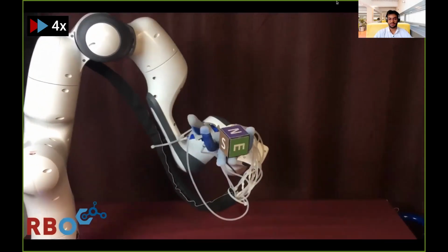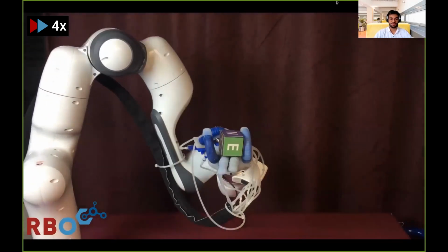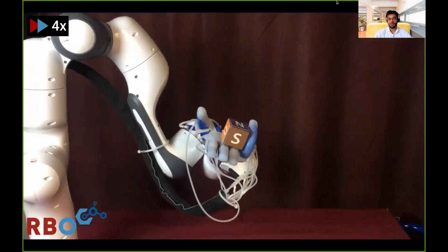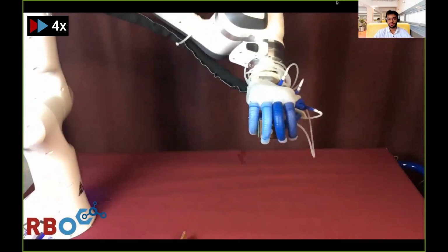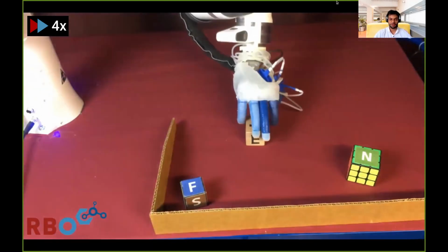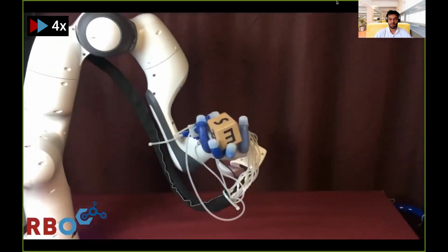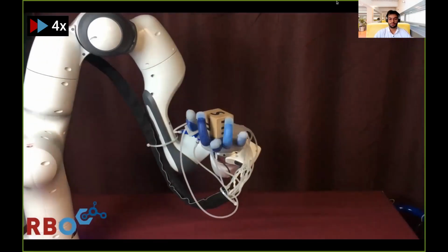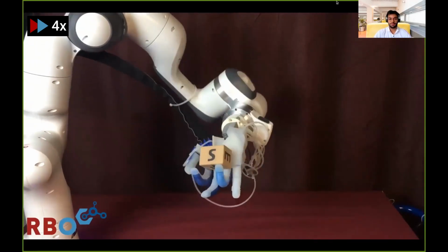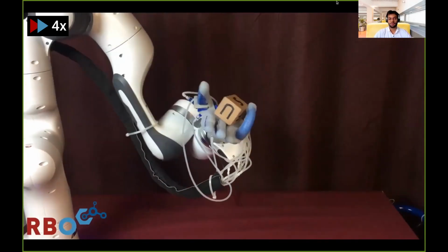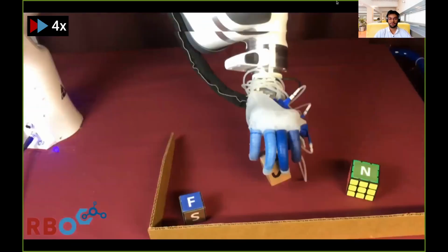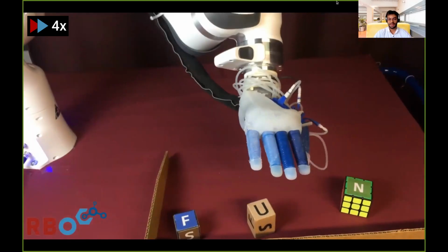These primitives act as funnels and they are sequenced using STRIPS planning. There is no feedback or sensing involved. And what makes these primitives robust is the compliance and the constraints offered by the soft hand. The key word is manipulation, because we execute the same primitives with identical actuations for all objects, unlike deep reinforcement learning where we have to learn a new policy for a new object. And looks like it handled it pretty well and is having a fun time.